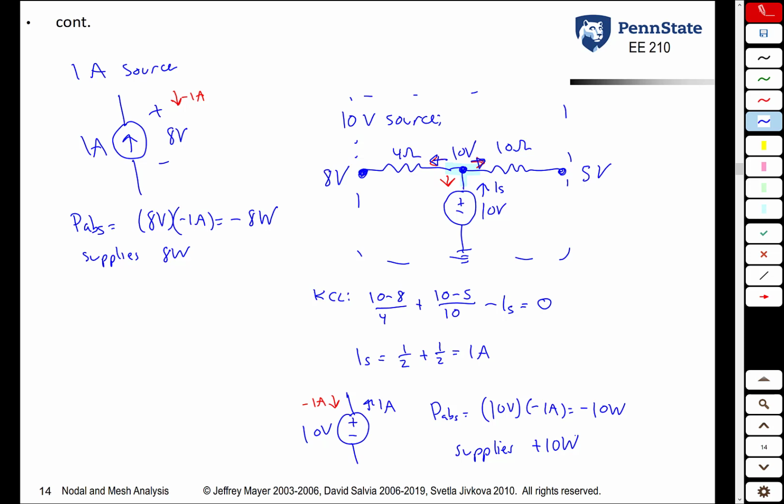So at this point, we've done a fairly simple example using the nodal analysis algorithm. We will pick this up next class to do more examples. We'll look at dependent sources, and we'll look at what happens when you have what's called a floating voltage source. That is a voltage source that is not connected to ground, and we'll see that that introduces some complications, and we need to change our algorithm a little bit to solve those types of circuits.